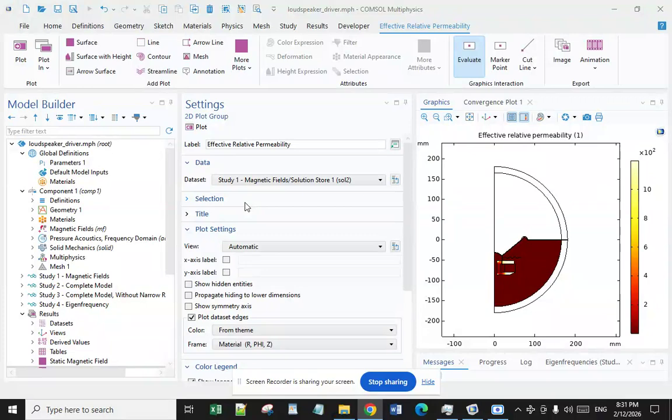The eddy current in the magnetic field experiences Lorentz force. In a microscopic view, the Lorentz force is applied on the electrons in the eddy current. In a macroscopic view, the Lorentz force is applied on the surface region of the material due to the interaction between electrons and atoms. The distribution of Lorentz force is primarily controlled by the design of the magnet and the electric coil, and is affected by the properties of the test material, the relative position between the transducer and the test bar, and the excitation signal for the transducer.